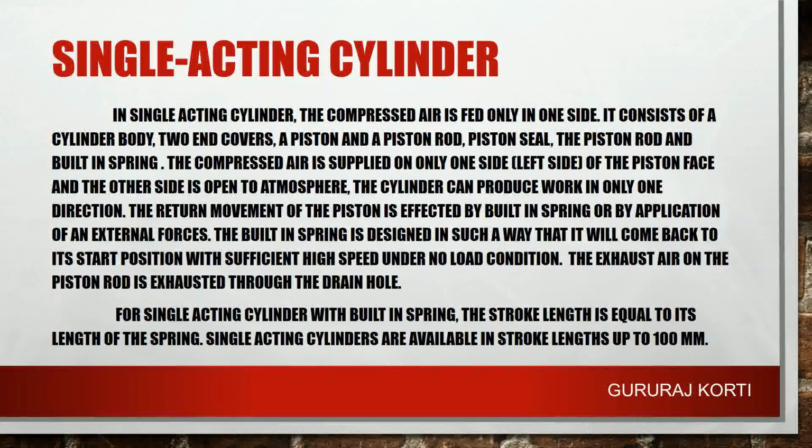The return movement of the piston is effected by the built-in spring or by application of an external force. The built-in spring is designed in such a way that it will come back to its start position with sufficiently high speed under no load condition. The exhaust air on the piston rod side is exhausted through the drain hole. For a single-acting cylinder with built-in spring, the stroke length is equal to the length of the spring. Single-acting cylinders are available in stroke lengths up to 100 mm.